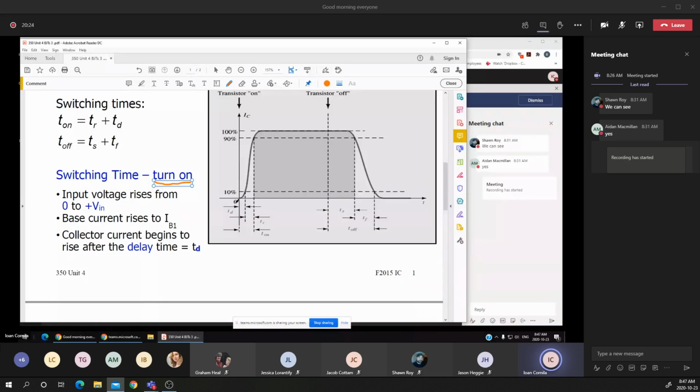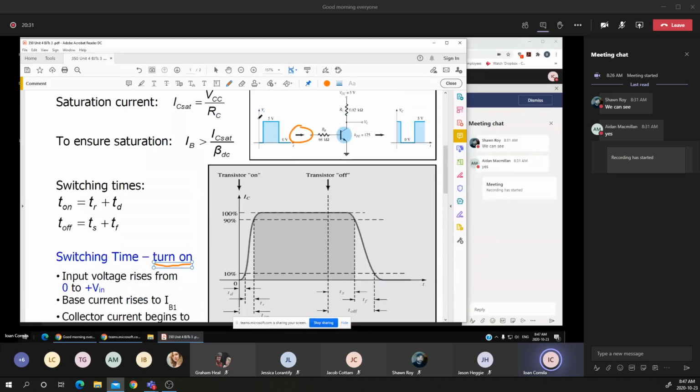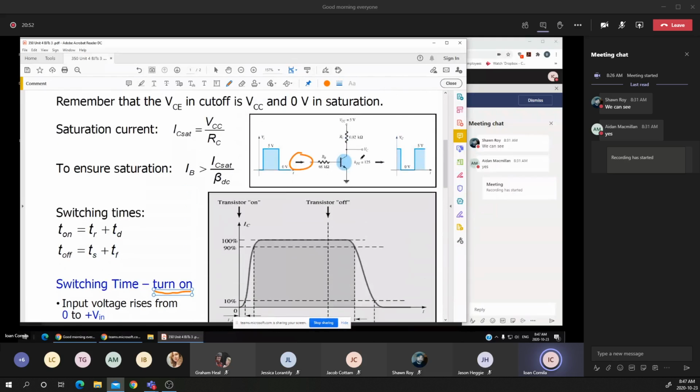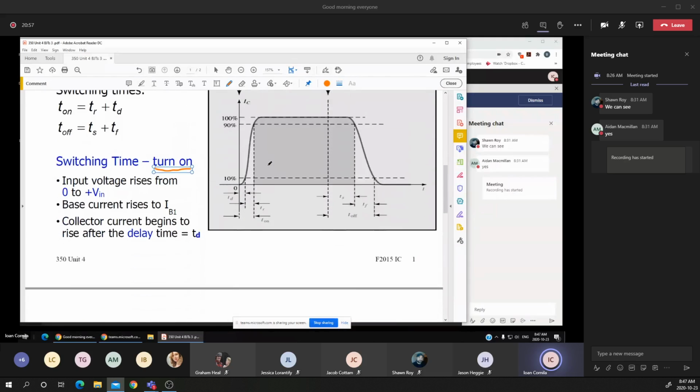You notice the response of the transistor to a step-up voltage, as in this diagram. A step up is a rectangular waveform, which will give a rectangular waveform on the output. At large frequencies, this output voltage will be distorted due to the capacitance, due to the amount of time the transistor requires to respond to a fast change on the input voltage.